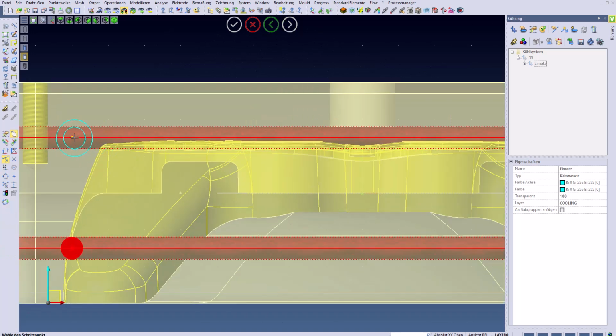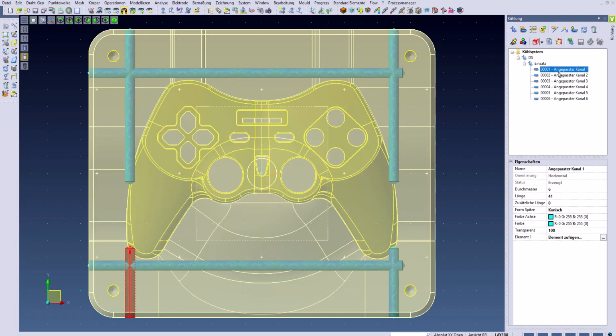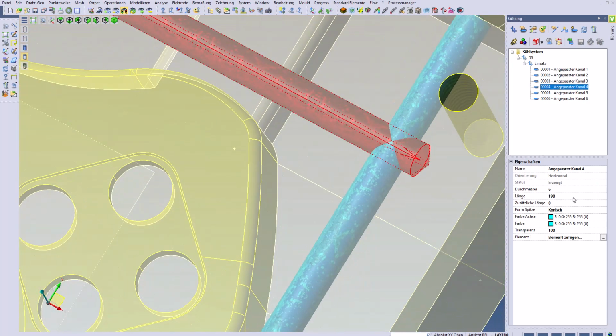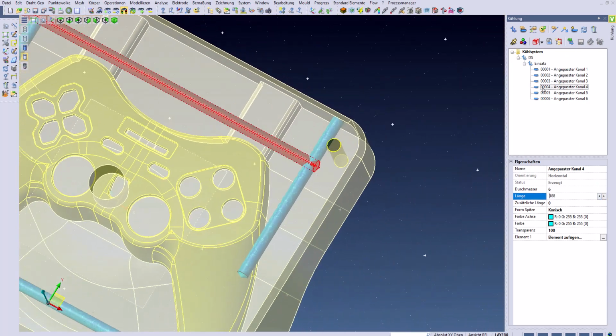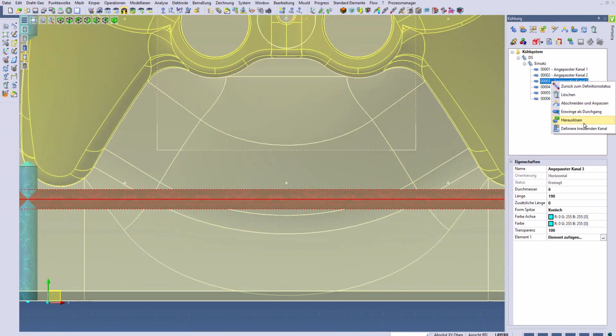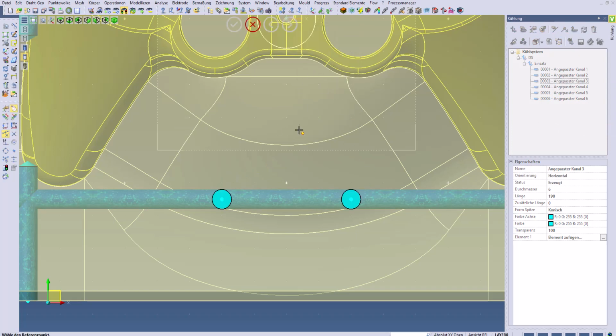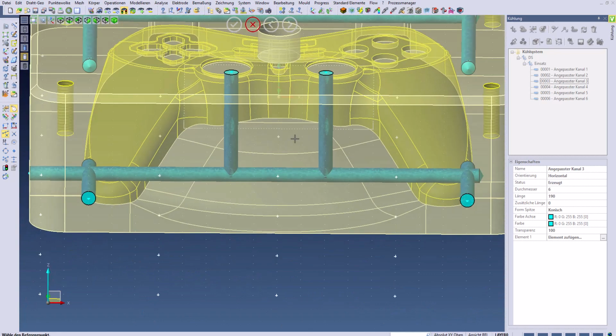Cooling channels can be easily inserted using a dedicated cooling wizard. Sketch the path of the cooling channel, and the wizard gives the designer complete control over position and sizes, providing automatic proximity checks to ensure cooling lines do not interfere with other tooling elements. Standard cooling line fittings can be easily inserted from leading supplier libraries.